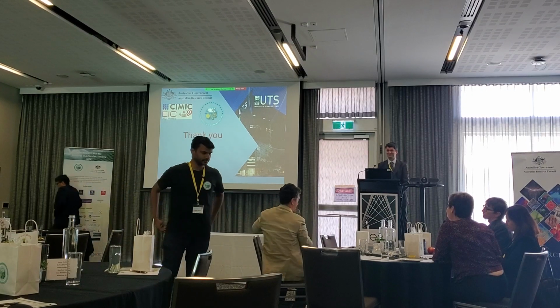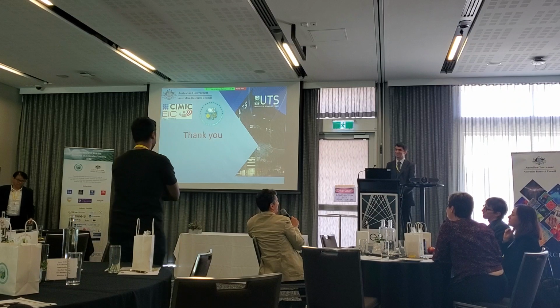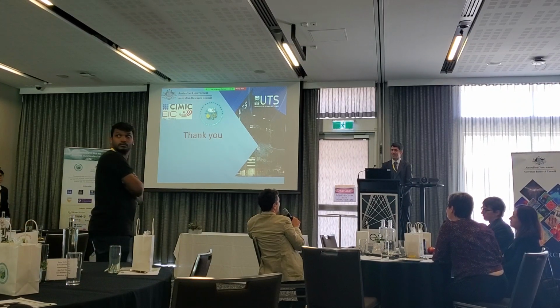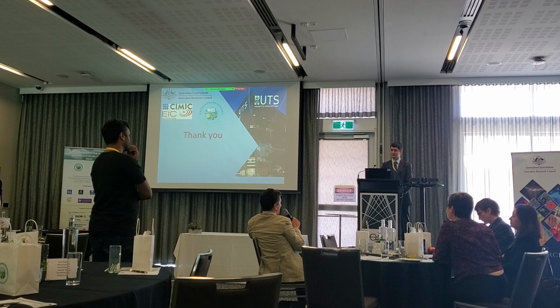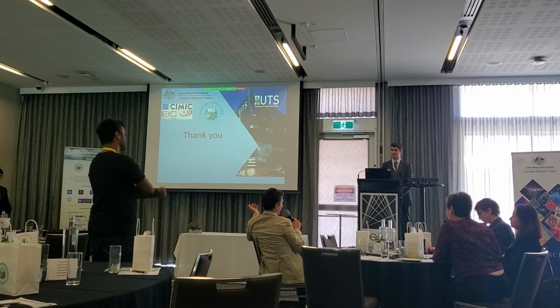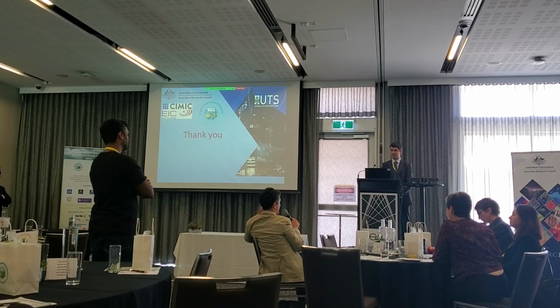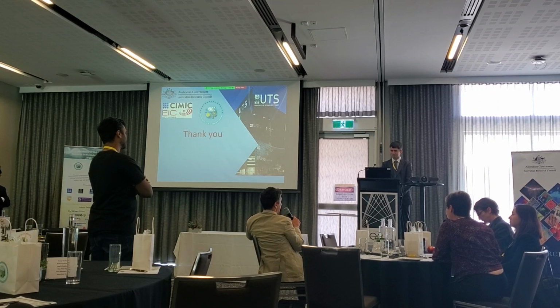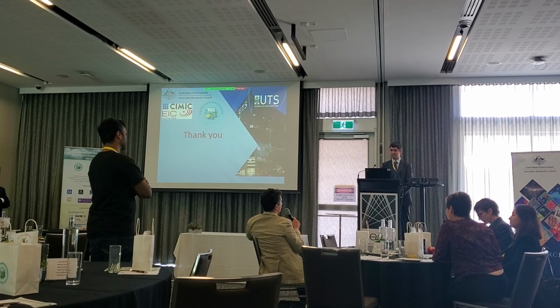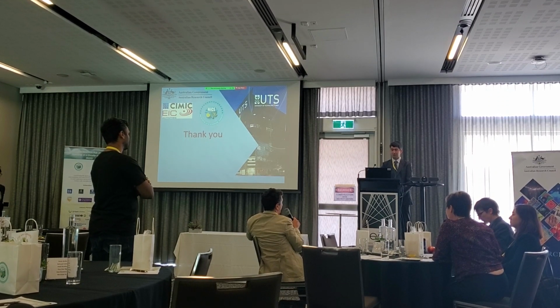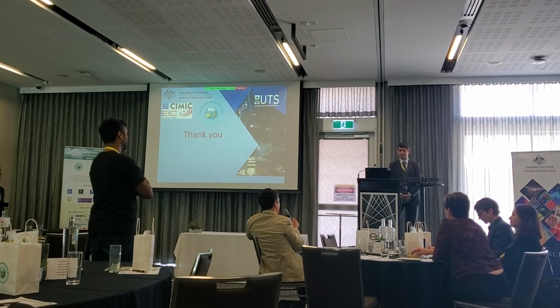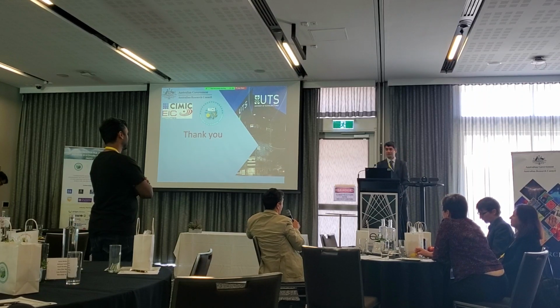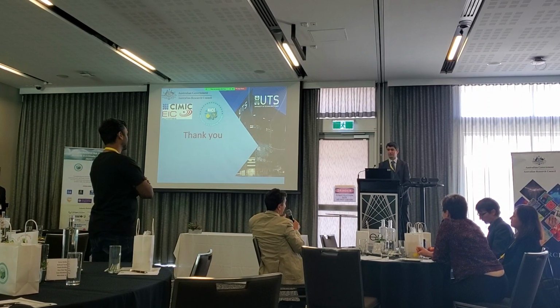Thanks, Reza. I know we already talked, but I just had another thought. The Yugo process basically takes the urea, converts it into ammonia and carbonate. Then we get the ammonia out because we want to recover the nutrient. And we have a byproduct which is rich in carbonate, pH close to 10. Could that work? Because you really don't want the ammonia in your system. So it might be better just to work with what you discard already, because all you want is the carbonate.